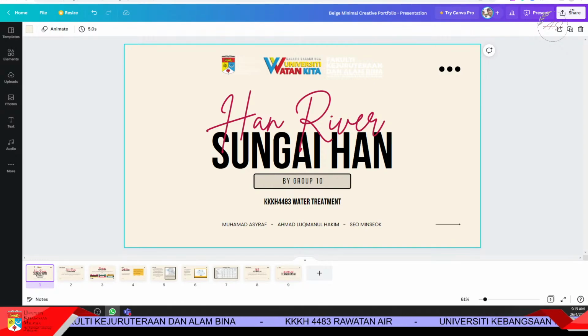Okay, so we're moving to the water quality of Raub's Fraser's Hill. Water samples were collected from 9 selected stations around the Fraser's Hill corridor. River water samples were collected about 10 cm below the water surface using pre-cleaned 1 liter high density polyethylene and glass bottles. So there are a total of 9 stations. Next. So this is the map of study location and sampling points. Next.